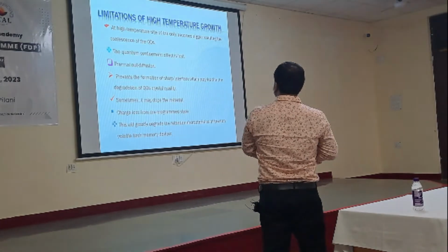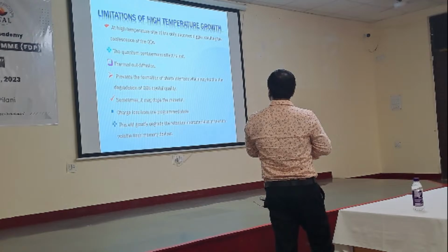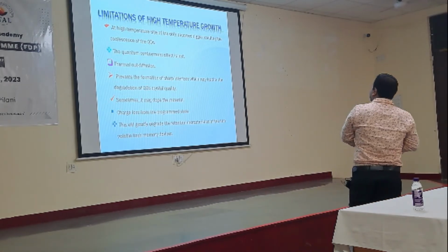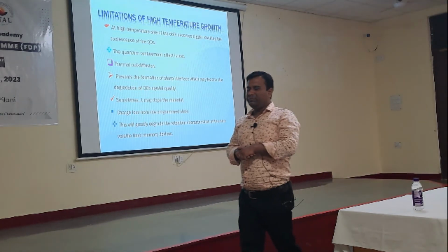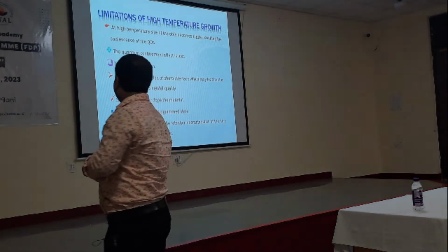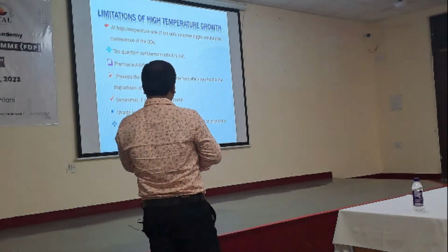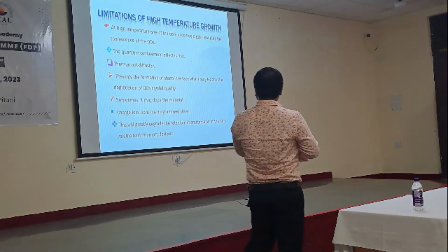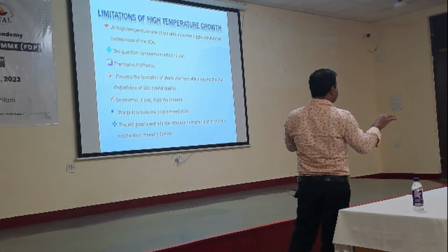Next. Now limitations of high temperature growth, that is from the literature survey. If you see in the literature, people are using indium arsenide quantum dots rather than metallic nanoparticles, and in all the cases people have used very high temperature growth, more than 500 degrees centigrade. But in my case I have limited my growth temperature to 380 to 500 degrees, because if you increase the temperature, your quantum confinement effect will be lost and your dot size will get bigger.